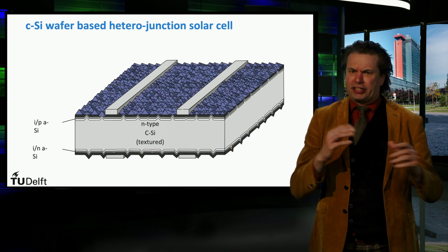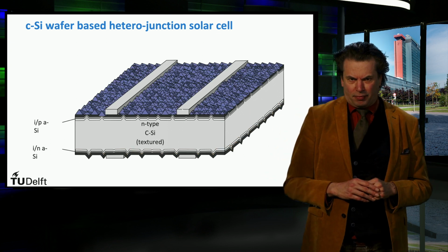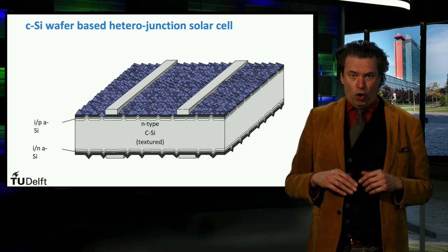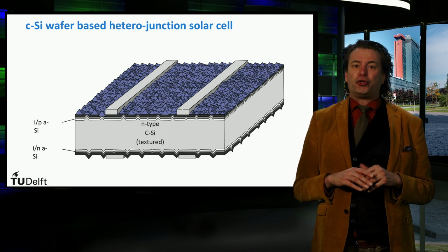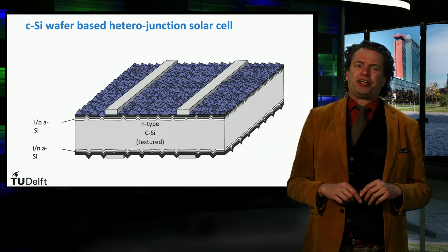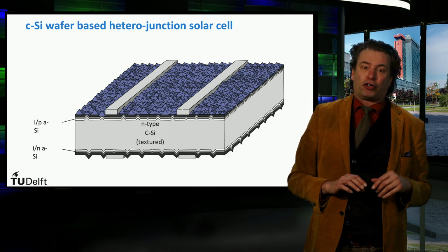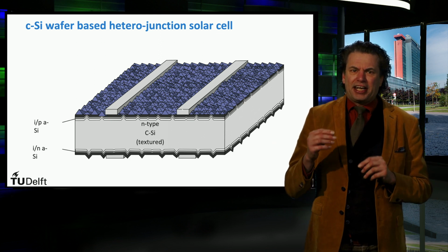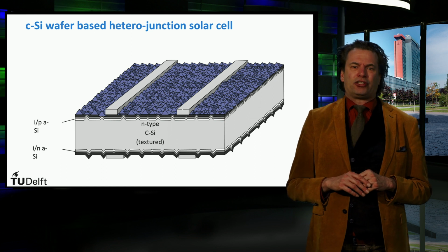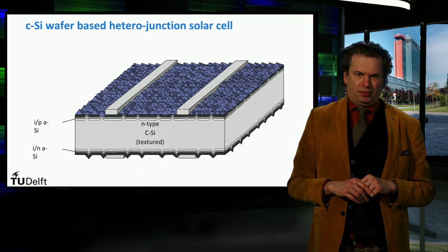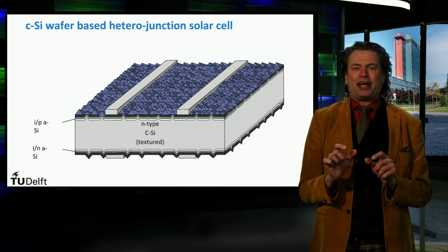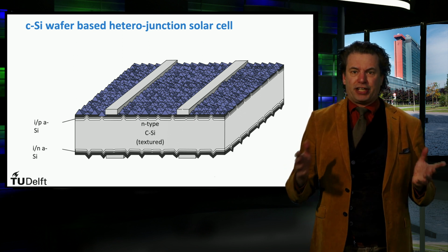How do the charge carriers travel to the contact? The conductive properties of the p-doped amorphous silicon are relatively poor. In the homojunction solar cells, the diffusion to the contacts takes place in the emitter layer. In contrast, in a heterojunction solar cell, this occurs through a transparent conductive oxide material like ITO, which is deposited on top of the p-doped layer. The ITO is needed as the conductivity of the p layer is too poor. This results in such small diffusion lengths that the practical metal finger spacing cannot be achieved using the p layers. Therefore, the ITO is used.